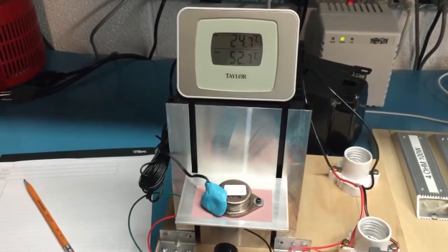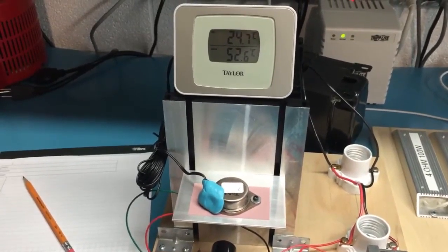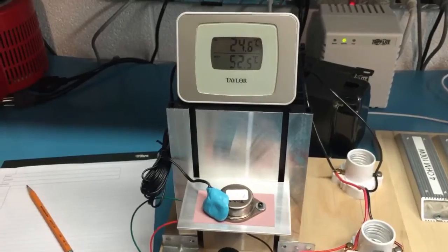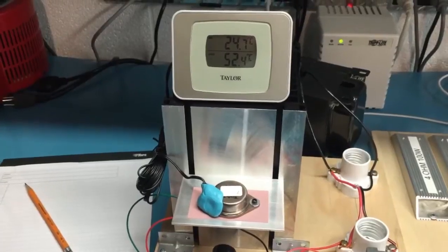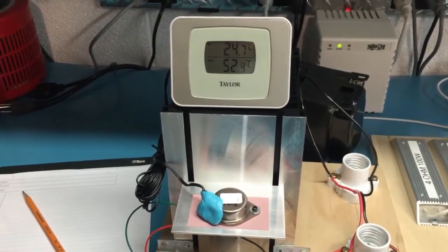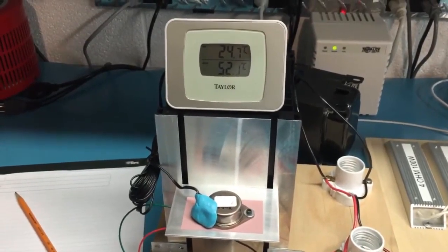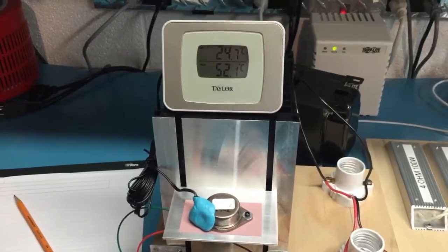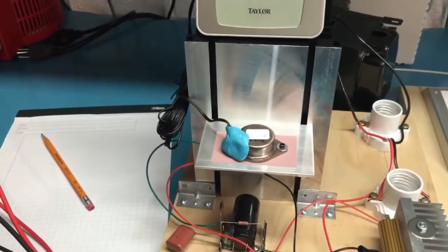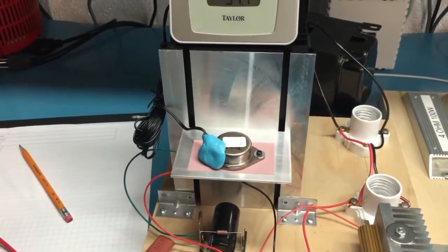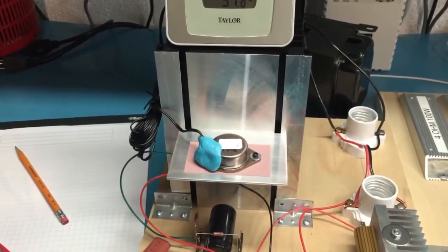Okay, I set up a little demonstration here of what is meant by positive temperature coefficient. I've got a little circuit built up here, and there's an indoor-outdoor thermometer on top of the heatsink. The indoor temperature is the temperature here in the lab, and the outdoor temperature is the temperature of the case of that 2SK180, which is just attached to a temperature probe, which is stuck to the case with a glob of blue tack.